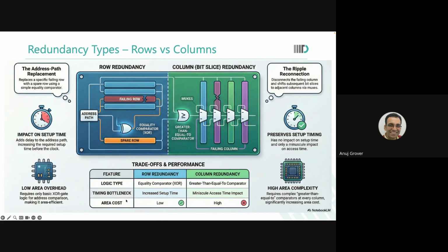In terms of power, both would be equivalent, except that power consumed during setting up of column redundancy is going to be higher because more comparisons are happening, more leakage is coming in. So those are secondary impacts, not the primary impact. It does not change much about the dynamic power of the network. Are you with me?